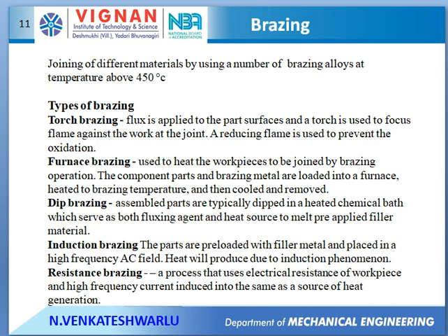And we have different types of brazing based on the heat source: torch brazing, furnace brazing, dip brazing, induction brazing, resistance brazing. In torch brazing, the source of heat is a flame supplied by means of a torch.